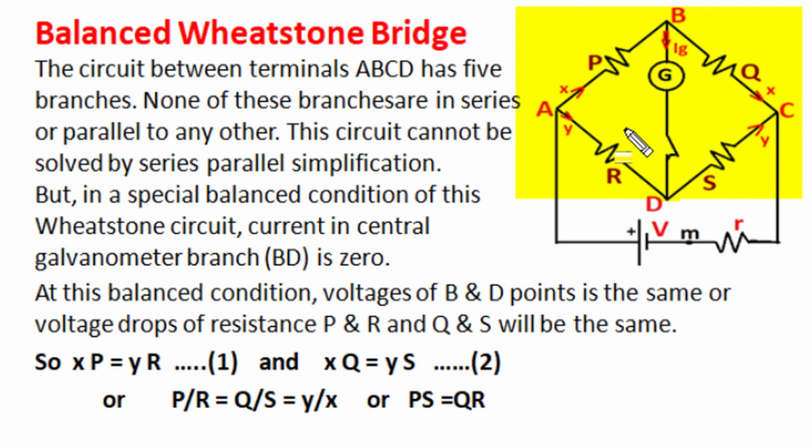But there exists a special condition of this circuit as studied by scientist Wheatstone, where node B and node D get identical potential and the potential difference across G resistance between B and D terminals becomes 0. So there won't be any current flow in this galvanometer section, and a galvanometer with null deflection indication can confirm this particular balanced condition of Wheatstone bridge.